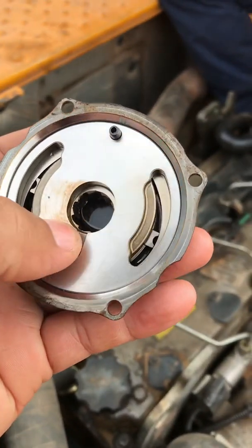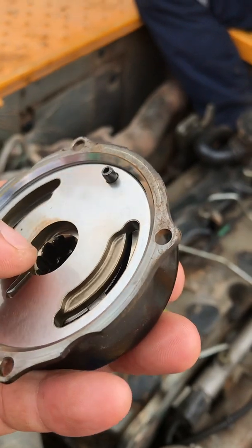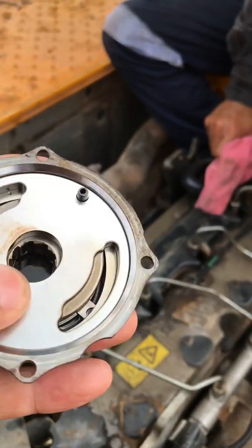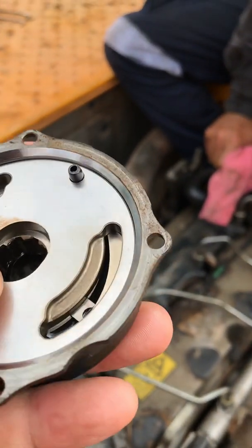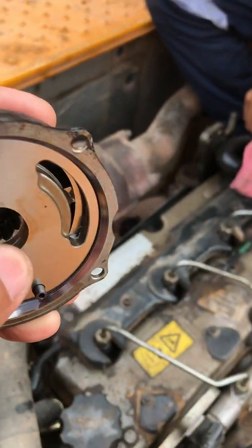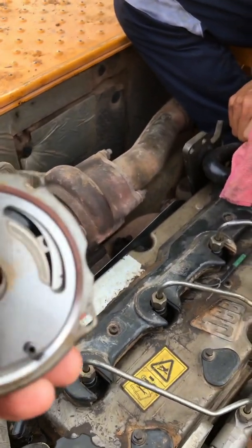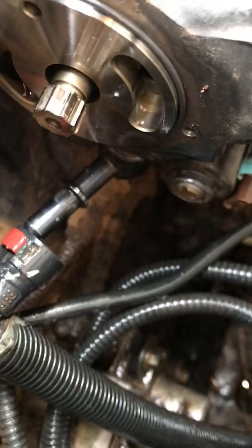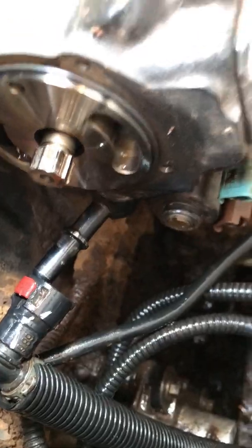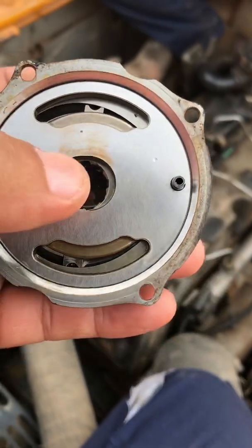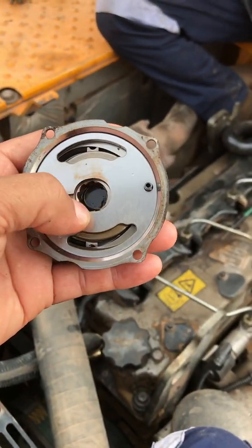So here, as you can see, the supply has broken. It's like that because of the quality of the pump, and also the fuel quality being a little low. Poor fuel quality can damage the pump very quickly. Here the supply is loose, and look at the pump side over here. The issue I told you I suspected for this pump, that's why I take it out. Now I found the problem, so I will change this pump assembly, then we'll try to start again.